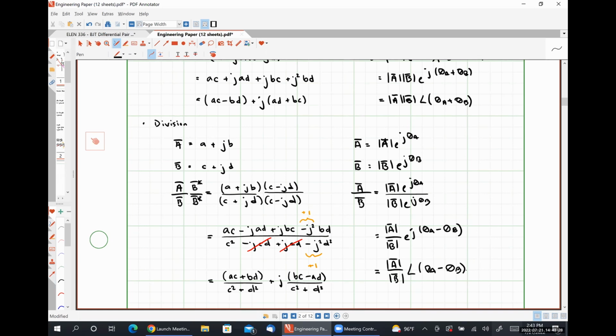There's a setting in the setup function where you can choose what type of complex number result you get, either polar form or rectangular form. Use whichever one you're comfortable with, and then there is a conversion button on your calculator, usually hidden inside a menu, that will let you convert from rectangular form to polar form and from polar form to rectangular form. So effectively, you can set your calculator in whatever mode you're most comfortable getting the result in, and then get the other form with a very quick conversion.